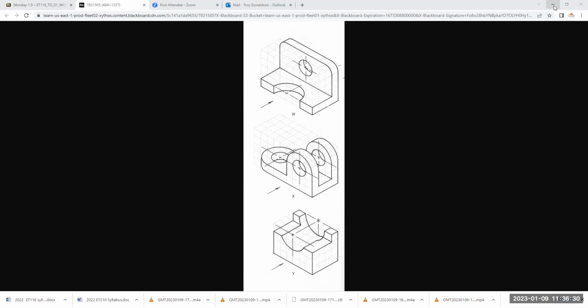So now I'm 1:5. I have determined 1:5 works good here. I can now place a dimension. So I'll just set one. Now that's going in 5 times bigger than 1/8 of an inch, right? Because the drawing gets shrunk 5 times to get onto the paper. So it's going to look big here, especially if you're zoomed in. But when you go here, escape. That's where it's 1/8. Makes sense?